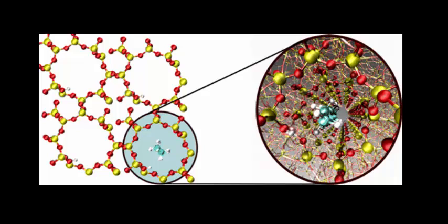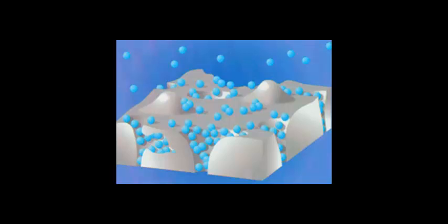The forces holding the molecular species on the surface can be weak or they can be quite strong. In the latter case, in particular, the absorbed molecules tend to readily form the self-limiting monolayers of interest for ALD, and such layers can be fairly stable at moderate temperatures. A physisorbed monolayer, on the other hand, may be readily desorbed if the substrate surface runs too hot because of the weak bonding forces. Once a monolayer of a first reactant is formed, then the introduction of a second reactant simply converts the first reactant to a layer of some desired solid material.